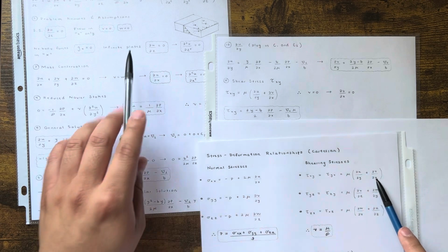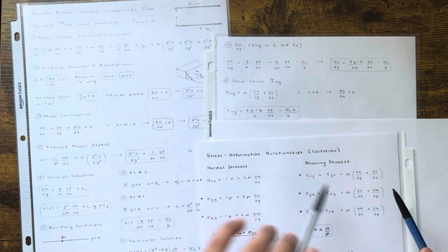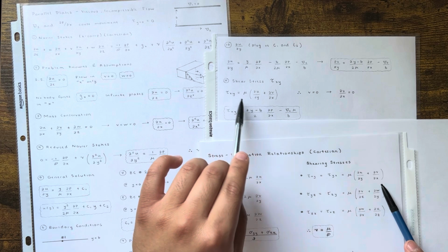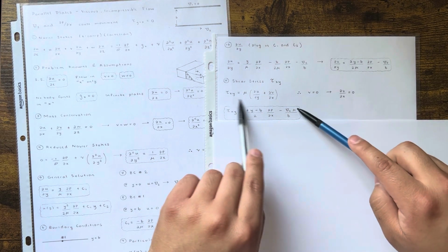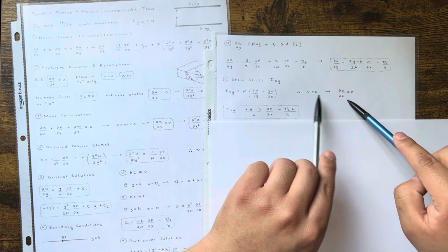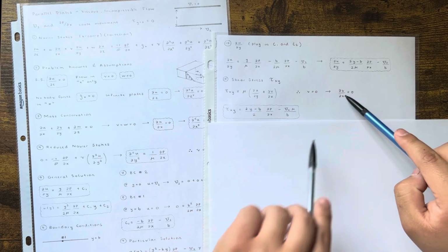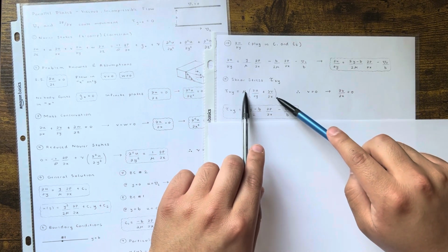We had stated that our v, the velocity in the y direction, was 0. So take the partial with respect to x of 0, and that's just 0. So now you're just left with this. It's kind of what I was doing here. This was the formula. Remember, v equals 0, so the partial with respect to x is just 0. Cool. So now that we have tau xy, ignoring this term, it's just this times this.